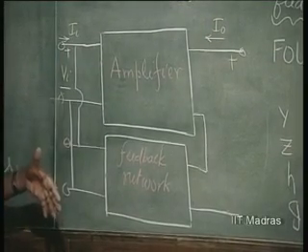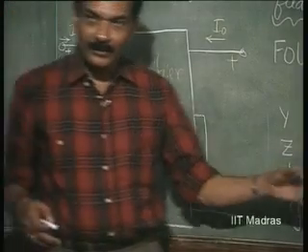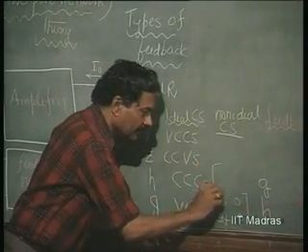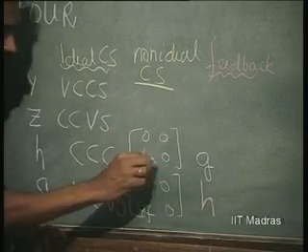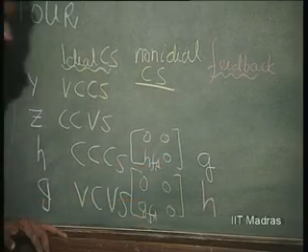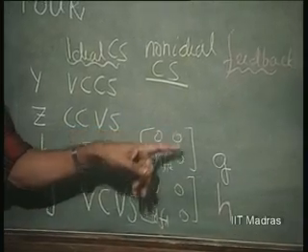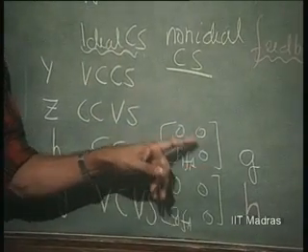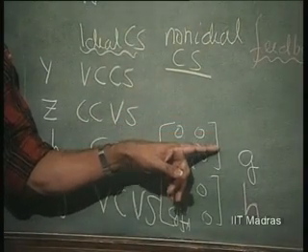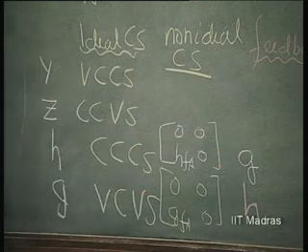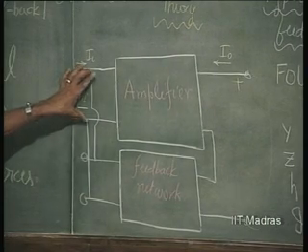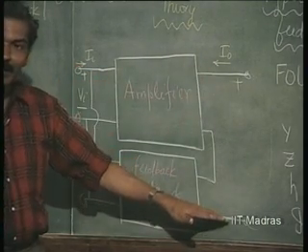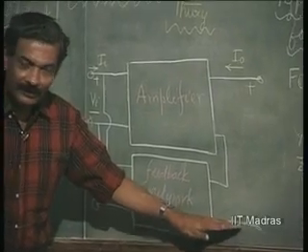You are trying to realize an ideal current controlled current source, because we had a non-ideal current controlled current source. Non-ideal, because these were non-zero and we wanted them to go towards 0. Then we apply G feedback. Why G? Because we wanted to reduce the impedance at the input so as to make it current controlled and increase the impedance at the output so that it becomes a current source.